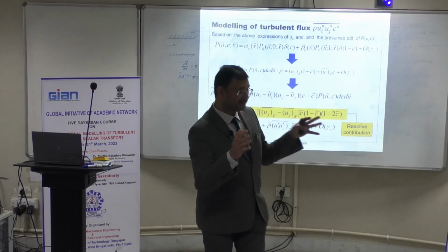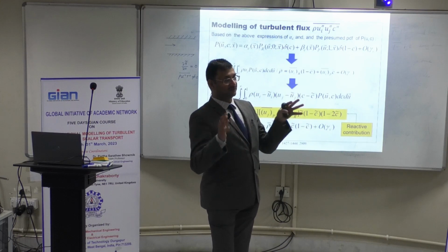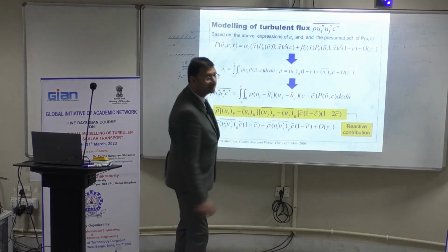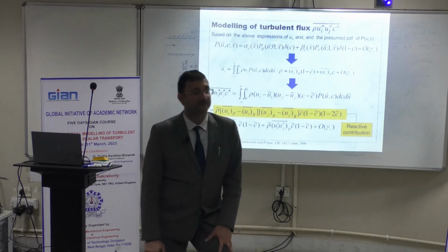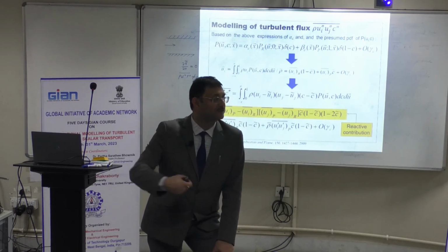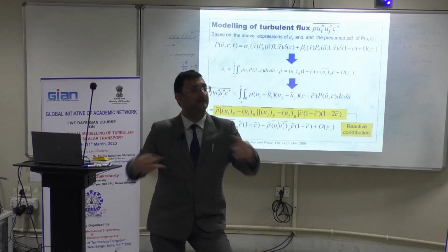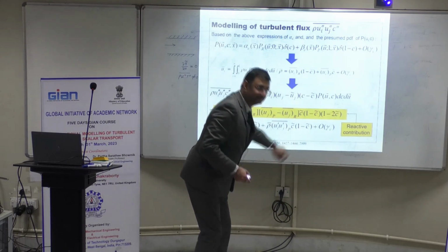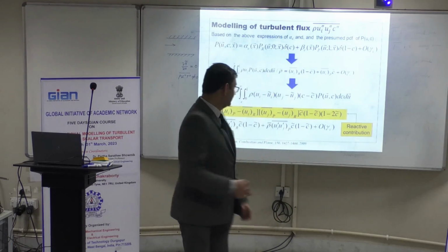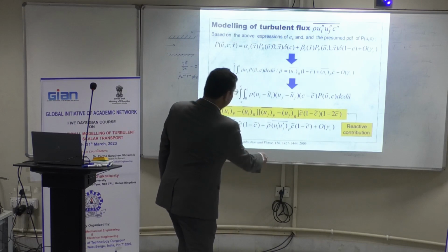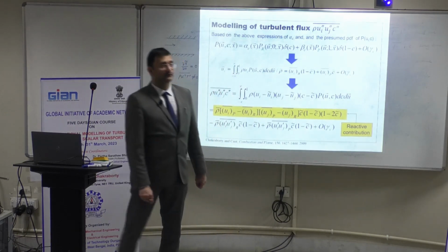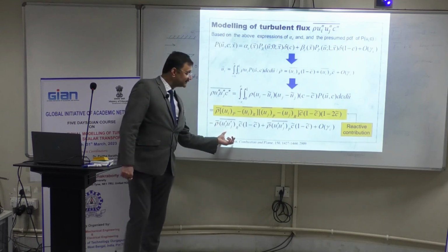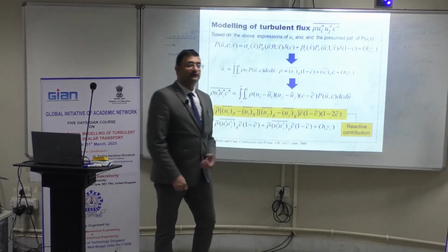This part originates because of the thermal expansion effect. And whatever is left here is basically the non-reacting contribution. That's the turbulence effect, and how turbulence interacts with the flame. That's why you have the heat release contributions as well. But in general, this part effectively is the non-reacting contribution. This is the Reynolds stress conditional on reactants, and the Reynolds stress conditional on products.